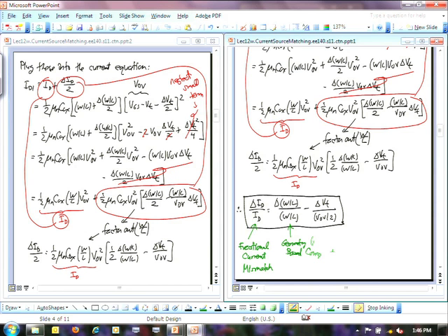That doesn't give you a lot of room to give yourself buffer for that channel length changes, which then changes this W over L1 versus W over L2, right? The threshold voltages are more difficult to control, etc. So analog design is just becoming more difficult for you as technology advances. But that's the excitement in analog design, because that means things stay interesting, right?